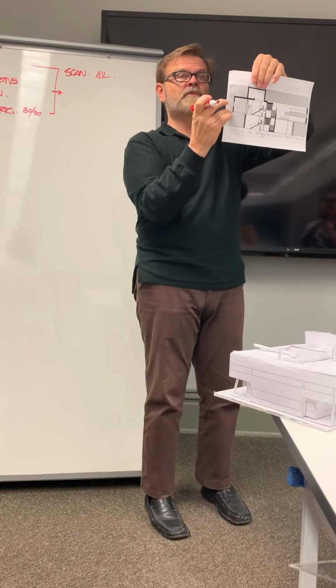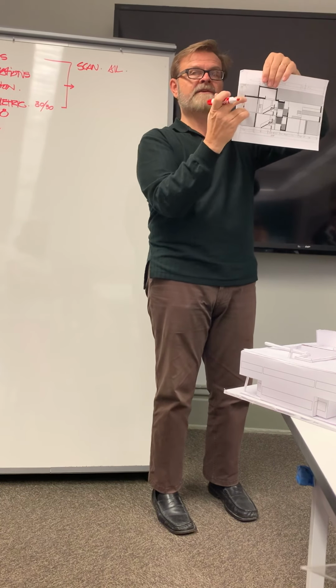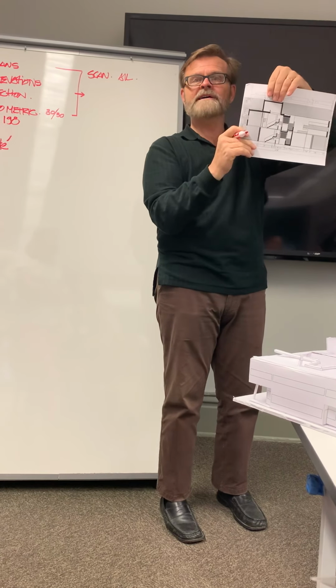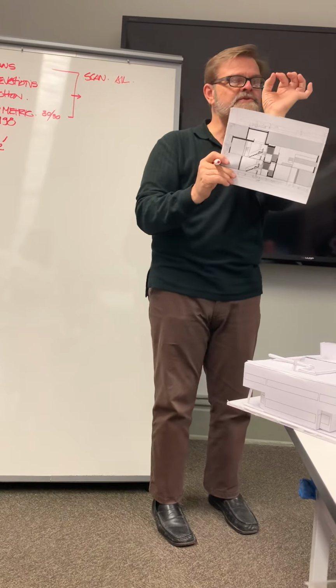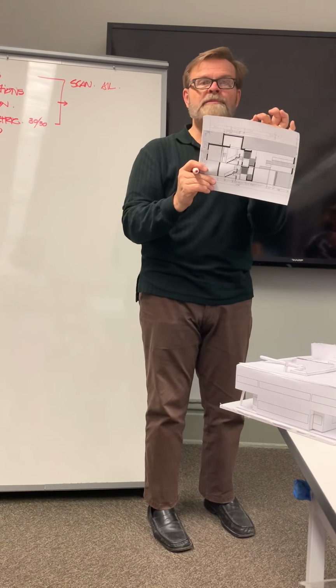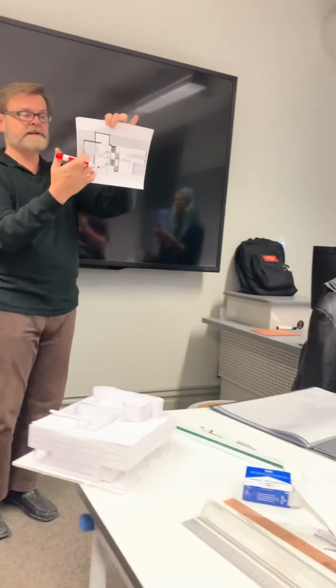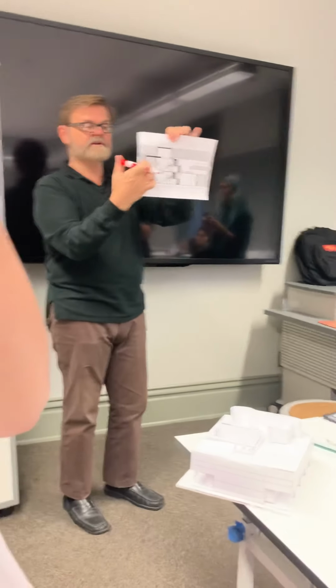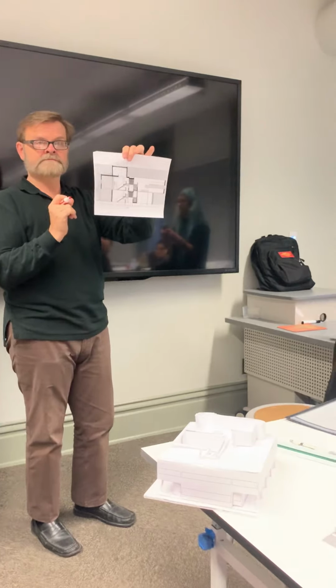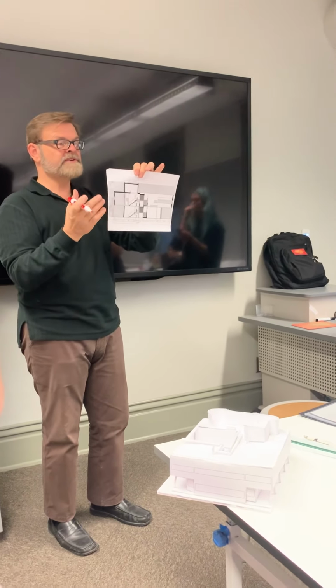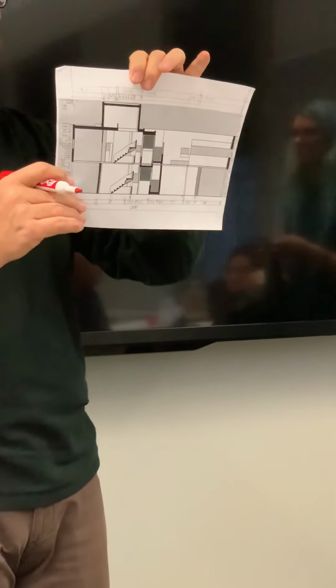The outside of the window frame, the inside of the window frame, and then we don't poche it because all there is, is glass. It's super thin, and we're not going to put a little black line there. Make sense? And then what we understand in this drawing is that if we were standing here, we could look out a window. Otherwise, from the interior's point of view, you haven't really told me anything, right? In this section, we're in a box with no windows. That is not true. We have a window. Okay? And so basically there it is.